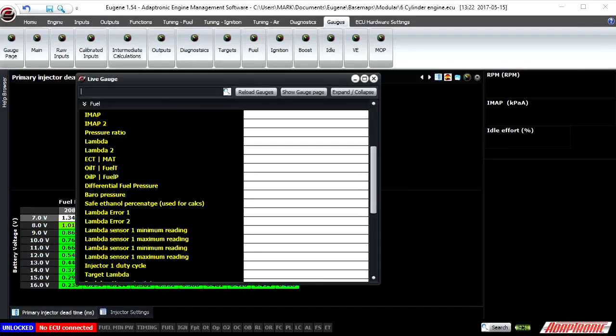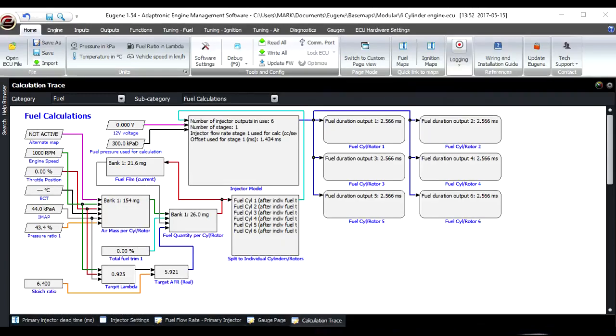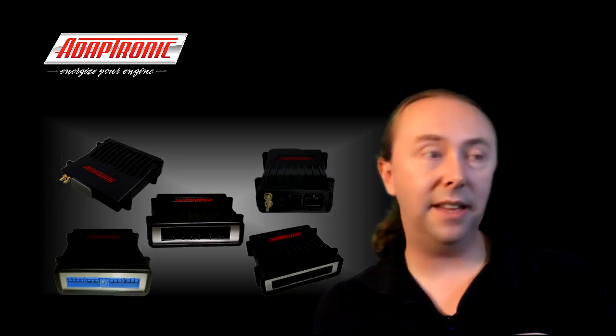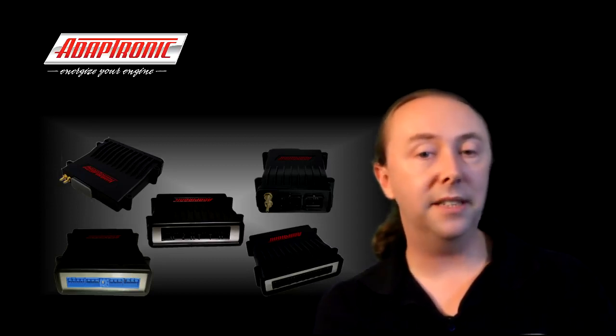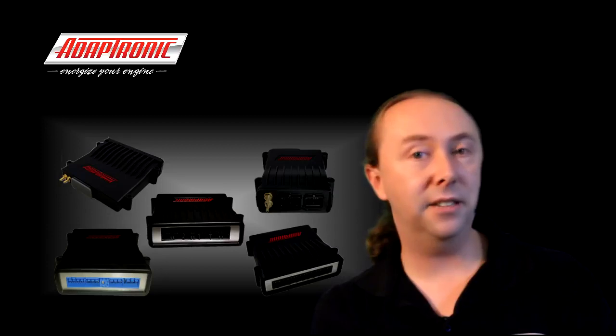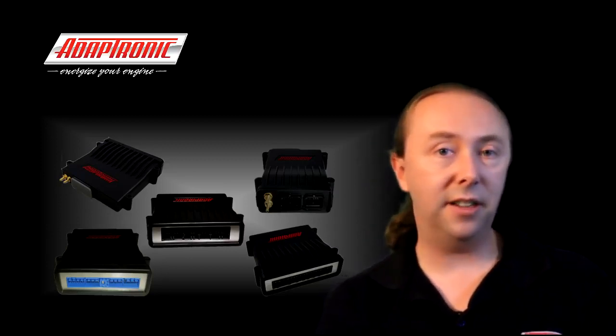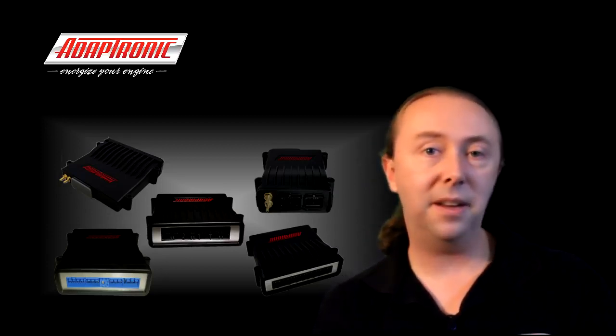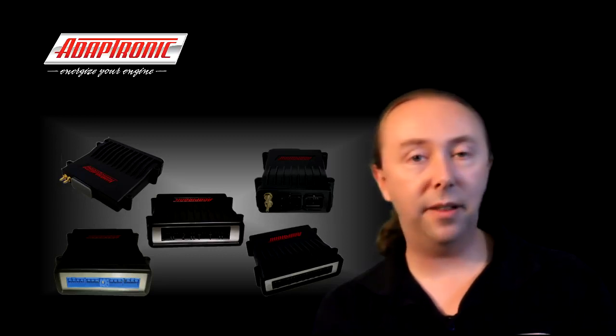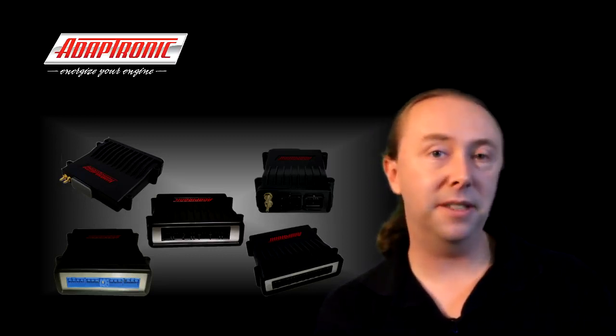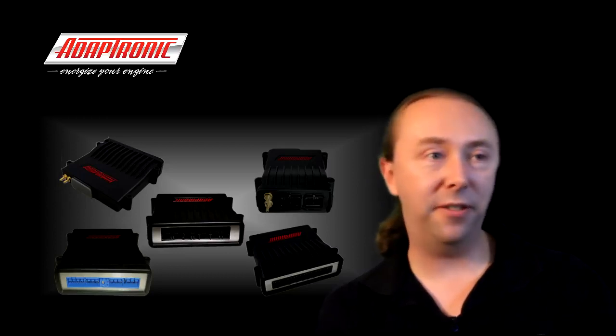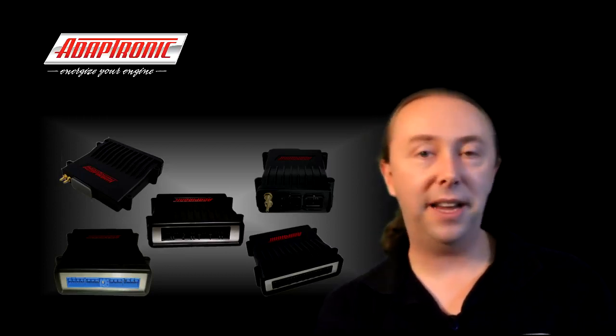Now, note that just like before I said you can look at the fuel density in the intermediate calculated values section in the gauge window, you can also look at the current flow rate and offset that the ECU is using as part of the fuel injector calculation. Now, one last point I'll say, which I think is a trick missed by a lot of tuners, is that watching differential fuel pressure is actually really instructive. I've seen tuners try to diagnose fuel pressure systems by running external gauges and that sort of thing, and watch it as an engine comes on boost, and then manually subtract the boost pressure from the fuel pressure that they're seeing to try and work out what's happening.